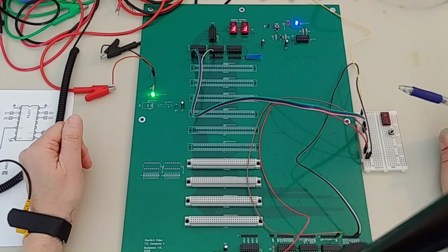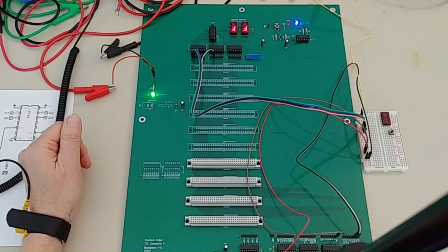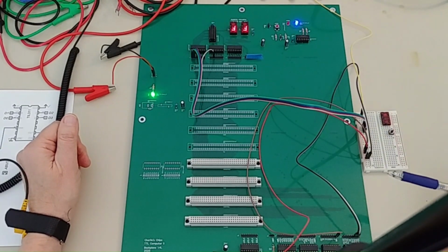I used a logic probe and looked at the U clock signal down here, and I'd bring that high, and it would remain high for a little bit. So what I determined was that because of the capacitance in the board, the pull down values were not low enough.